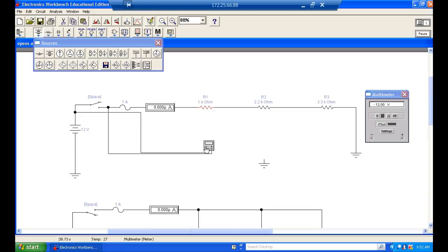I've got all these resistors out there. How could it drop 12 volts when, with Ohm's law, up until now we said resistors drop a voltage, and people don't understand a resistor only drops a voltage if there is a current flow through it. So if this guy here drops nothing, that's literally taking this guy and putting it right there. You understand? So this is why the applied voltage appears across.